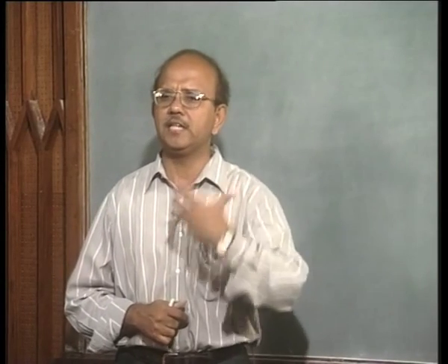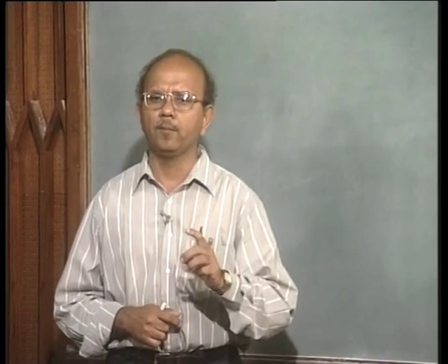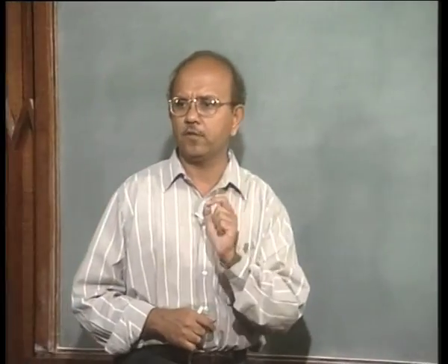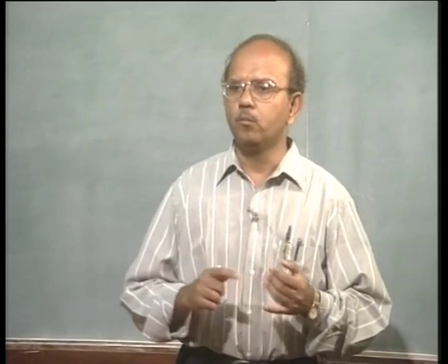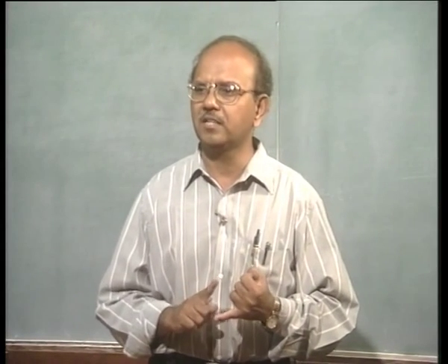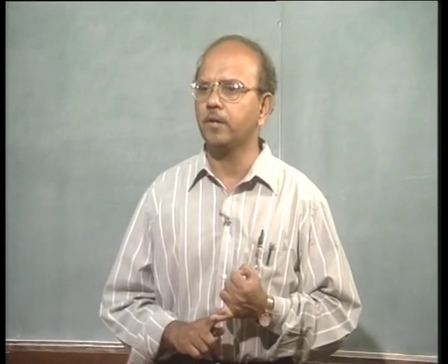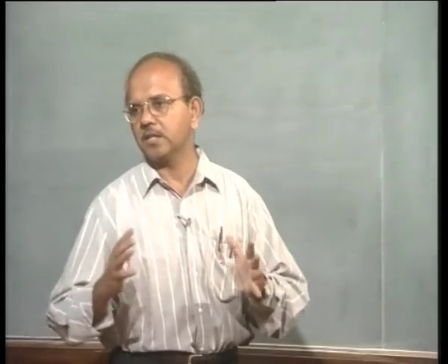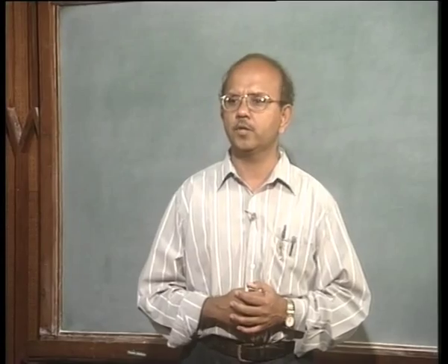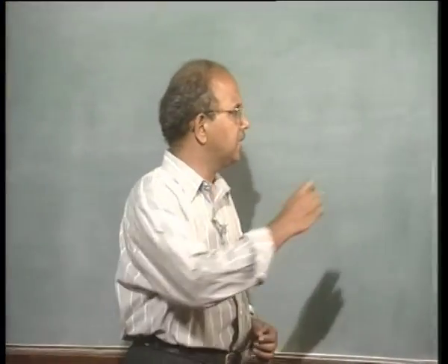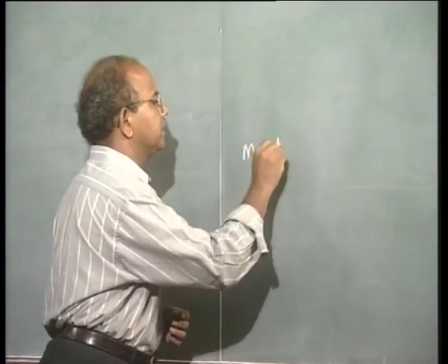There are various reasons why a problem becomes nonlinear. Watch this carefully. There are various reasons. Basically, the material that you are using may leave the elastic range, if you are using metal, and go into the plastic range, which results in what is called material nonlinearity.